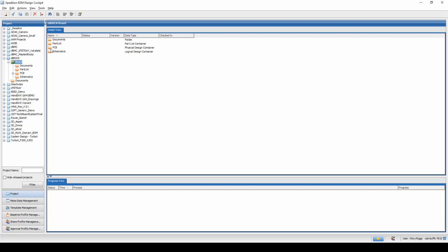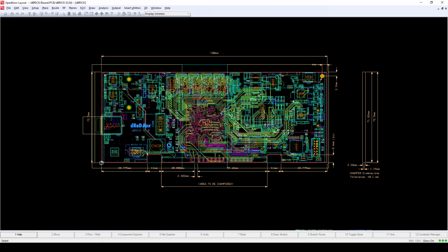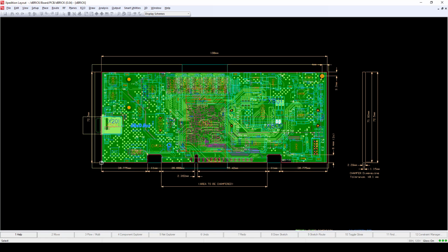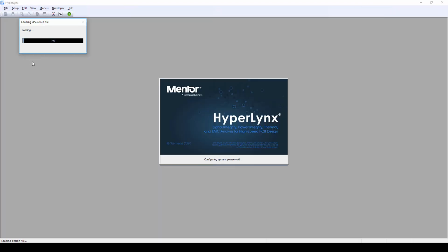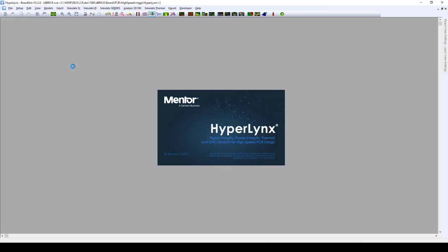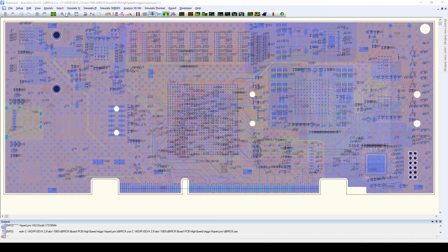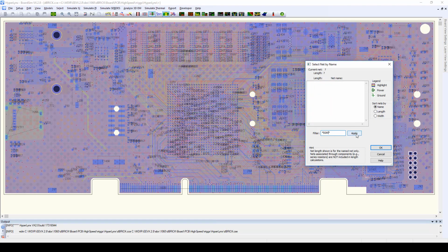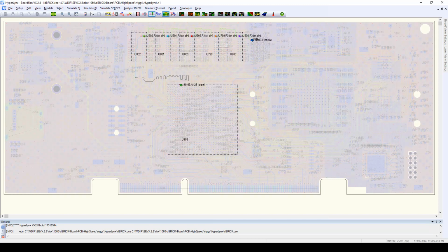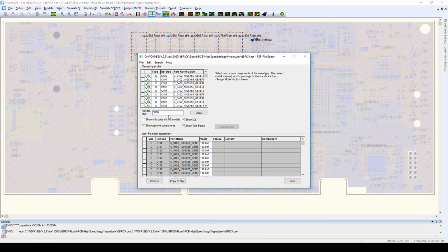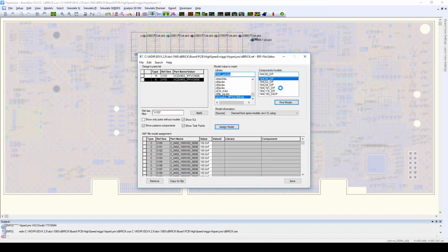New in VX 2.8 is an update to the integration between EDM, our data management tool, and the HyperLynx simulation family of tools. Three new data types are introduced in VX 2.8 for HyperLynx data checked into EDM together with the PCB. These separate and more specific data types for the main HyperLynx SIPI thermal tool, HyperLynx DRC, the automated rule checking tool, and the HyperLynx Advanced Solvers tool all allow for better understanding of the purpose of the files and for better handling in EDM.